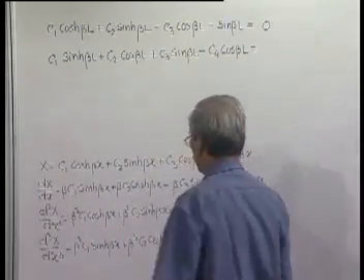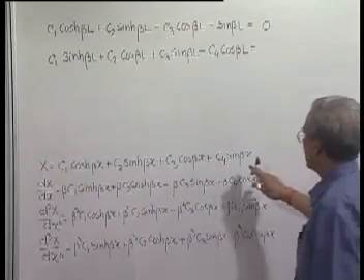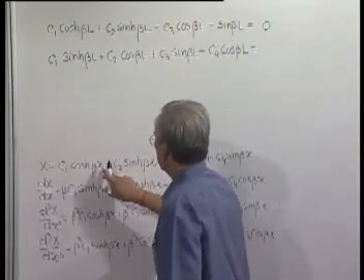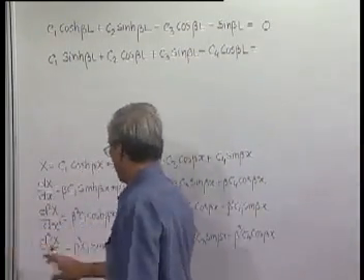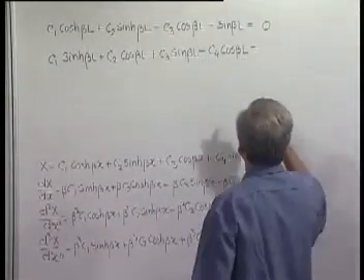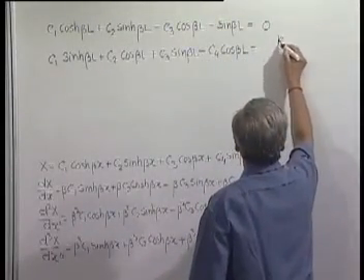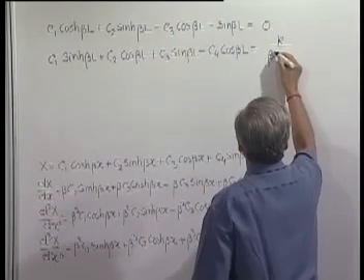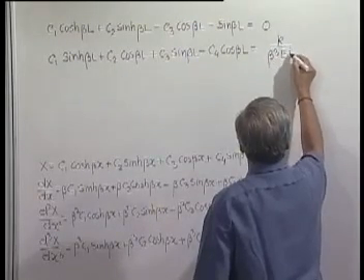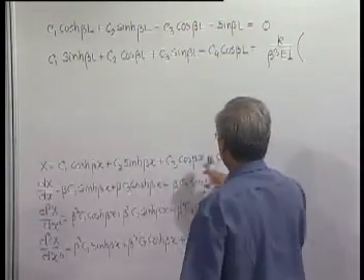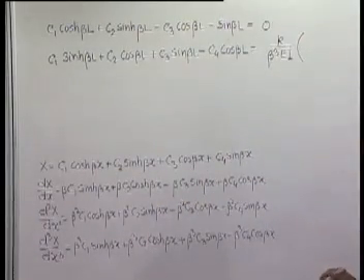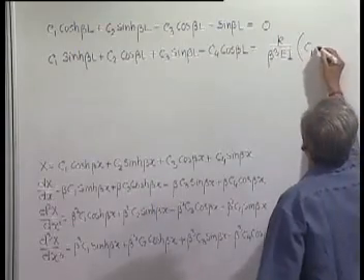This is equal to the value of x at small x is equal to L into k divided by EI, and that beta cube which we take common this side. So it will be k by beta cube EI and the value of x at x is equal to L. So it will be C1.